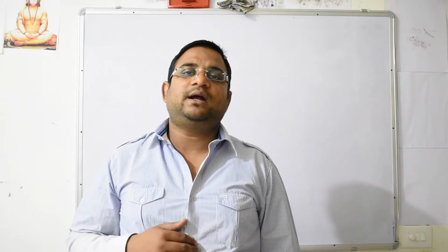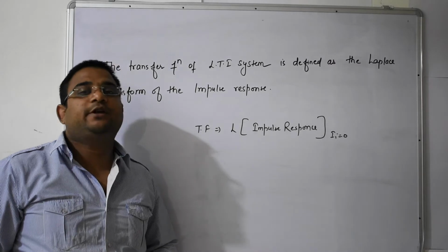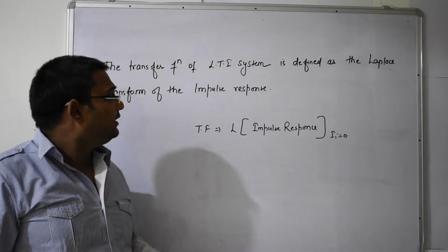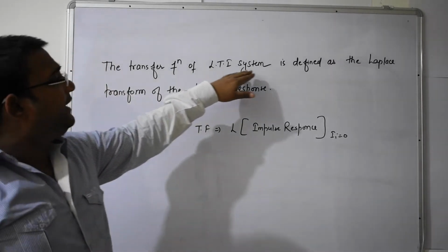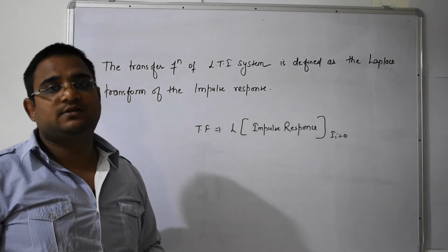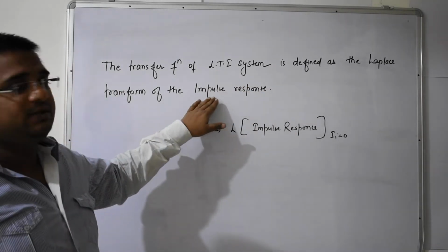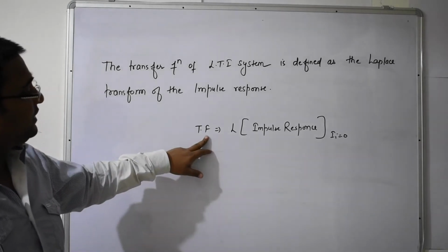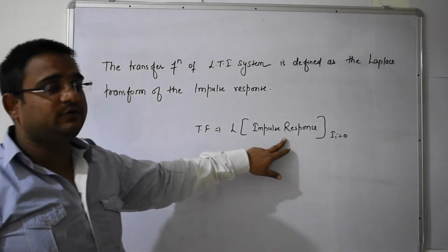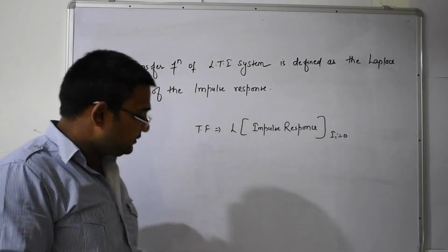So a transfer function of a system is defined as the Laplace transform of the output upon the Laplace transform of the input, with an assumption that our initial conditions are 0. So let us move further. There is one more definition of the transfer function. So a transfer function of an LTI system is defined as the Laplace transform of the impulse response. The transfer function is also defined as the Laplace transform of the impulse response.